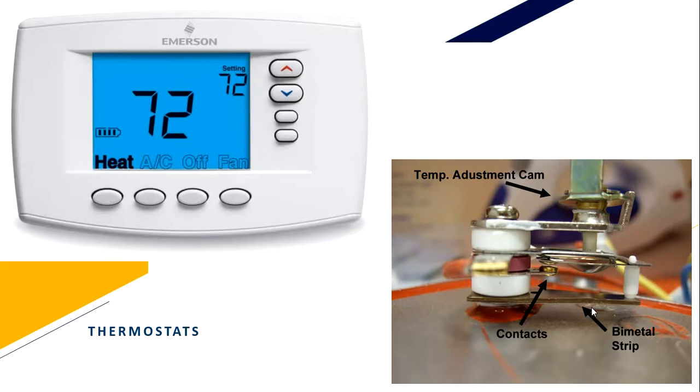Now, this switch is actually made of two different kinds of metals. Different materials expand or contract at their own particular rates. Different materials have different expanding or contracting rates. So when the bimetallic thermostat strip is heated, one of the metals expands more than the other.